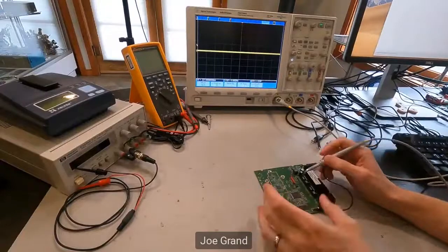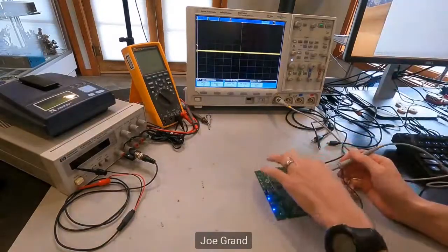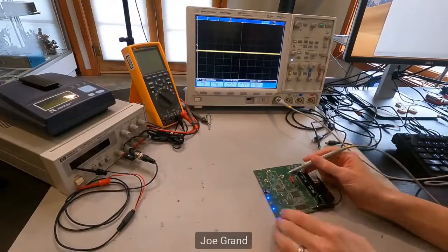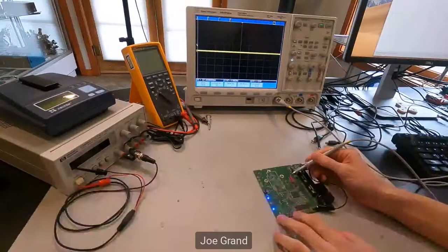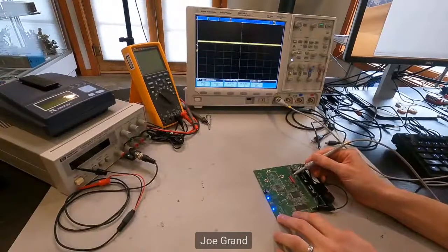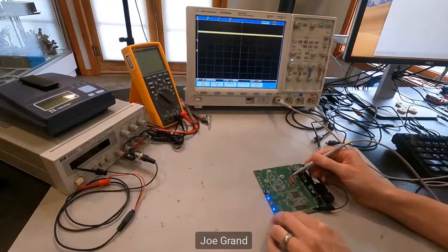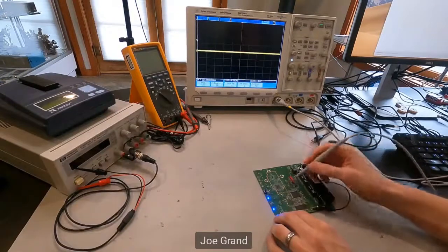So this system is already on. Usually what I'll do is look around and say, okay, this area is the power supply in the upper corner, so I don't really care about that. But I'm looking for the digital section, and I see some wireless stuff here. So I'm just going to use my oscilloscope probe and move up and down on all of the different pins, just to get a sense. This one's logic level high. It's just sitting there. A lot of times we're just going to see a static state, nothing going on. But I would end up making notes of this.